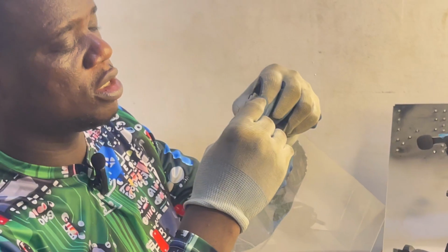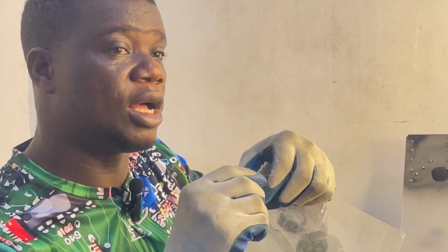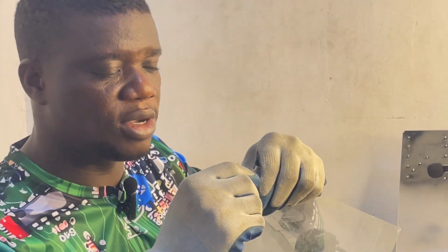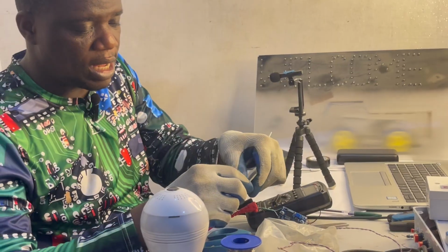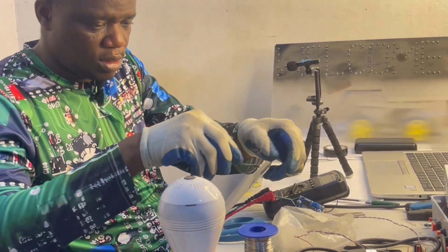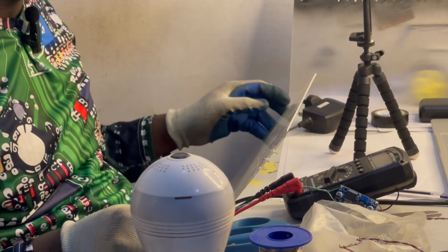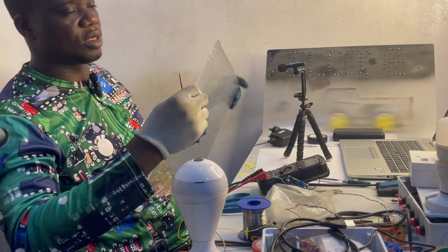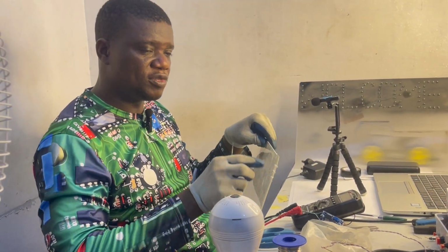What I'm doing now is called parallel connection. Parallel connection in the sense that anodes are going together, cathodes are going together. So once I'm done, I do it this way. Link all the anodes together, then use your soldering iron to solder it, which is not hard. So at this point, when you are done with the first letter, you move to the next one.